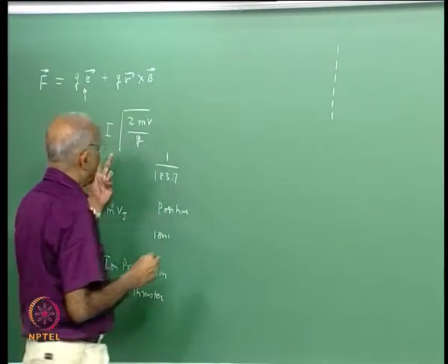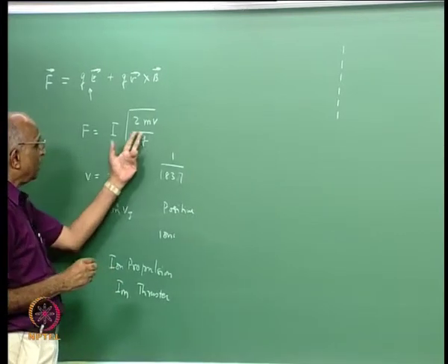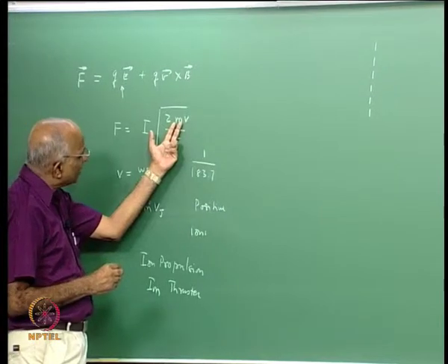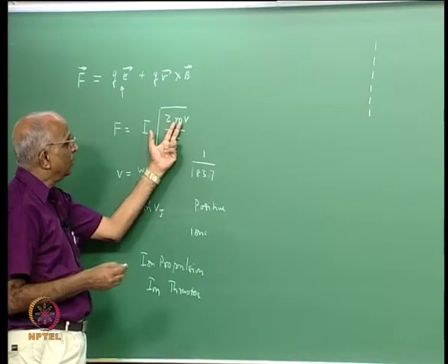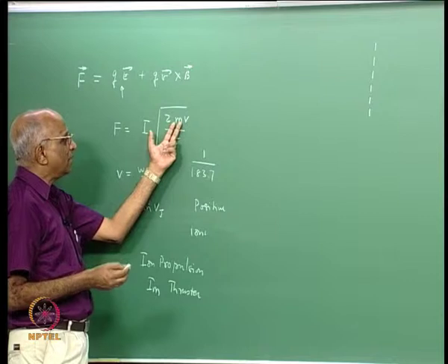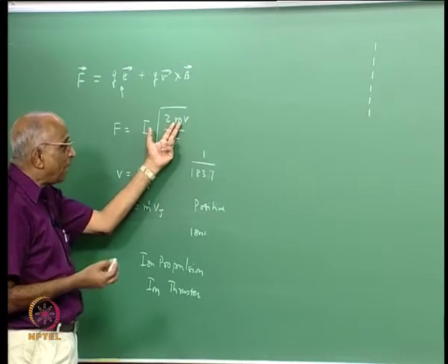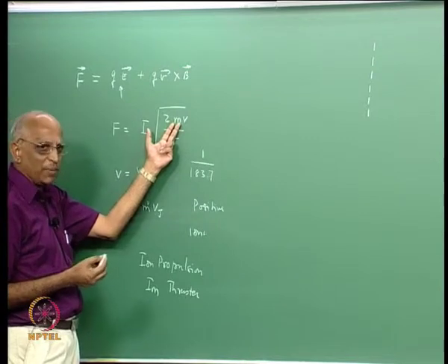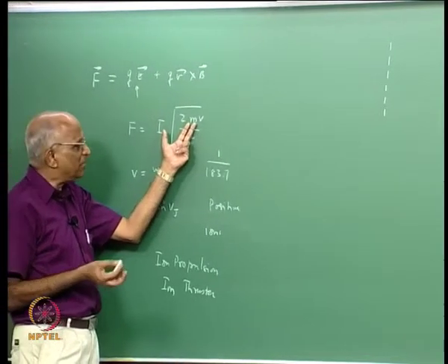Having said that, we also went one step further and said if I have to use this electrostatic principle and generate an ion rocket, now I call it an ion rocket because I know I am going to use positive charges. We said yes, we would also like to have substances whose molecular mass is larger or whose atomic mass is larger, and therefore I would rather have heavy substances like maybe mercury, maybe cesium, maybe xenon.